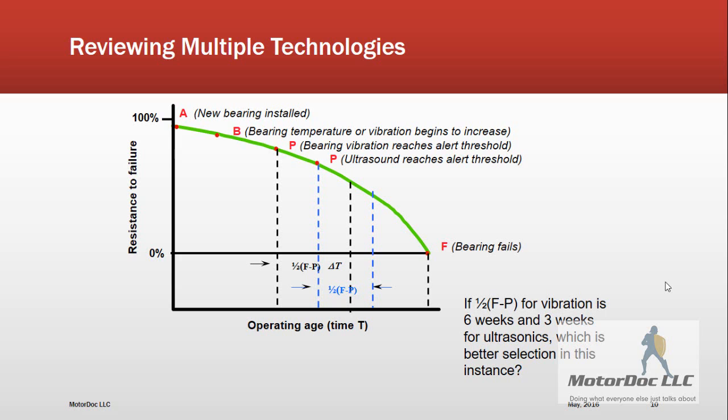It still must be noted that this is based upon the MTBF for the bearing failure. Some will fail sooner, some later, and some very quickly and may still not be detected. Therefore, the more critical the application, the more frequently testing should be performed. How to determine how many inspections is beyond the scope of this presentation. We'll cover it later on.